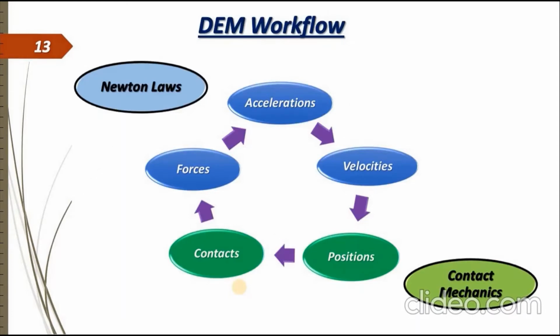Now, the DEM workflow, as can be seen here: if a particle comes in contact with the fluid or another particle, the forces acting on the particle can be used to calculate the acceleration, and based on those accelerations, the new velocities and positions of the particle can be calculated. And the DEM cycle continues based on Newton's laws and contact mechanics.